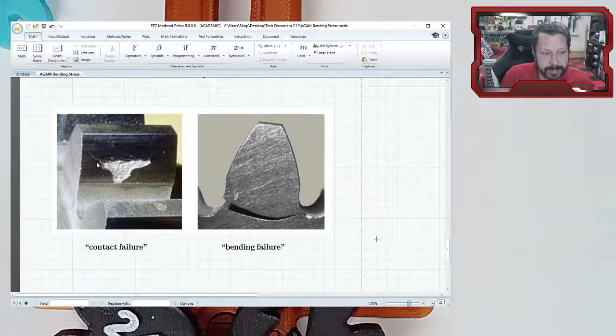Combine that with this line where the lubricant breaks down, or at least is not moving anymore, and you have metal on metal contact, and then you'll eject pieces of the gear tooth, and you end up with these pits. Sometimes they don't end up as this big chunk, but there'll be lots of little pits all the way across here.